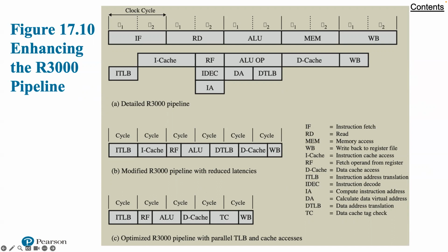shows that there is not only parallelism due to pipelining, but also parallelism within the execution of a single instruction. The 60 nanosecond clock cycle is divided into two 30 nanosecond stages: the external instruction and the data access operations to the cache, each requiring 60 nanoseconds, as do the major internal operations, the OP, the DA, and the IA. Instruction decode is a simpler instruction requiring only a single 30 nanosecond stage, overlapped with register fetch in the same instruction.